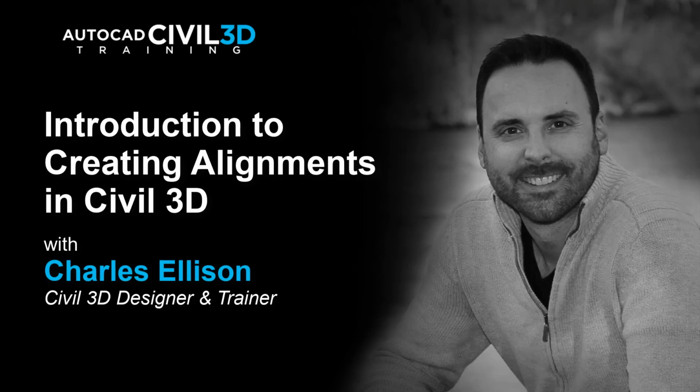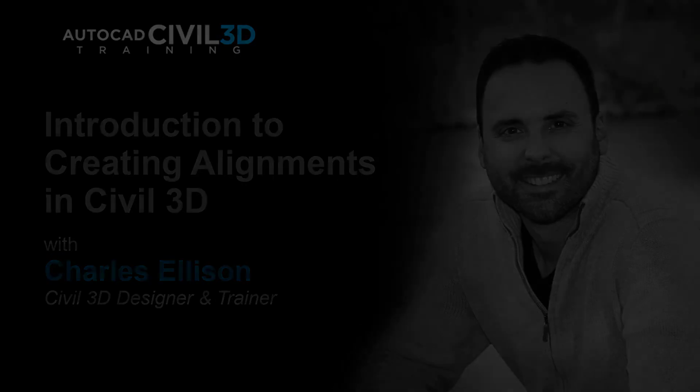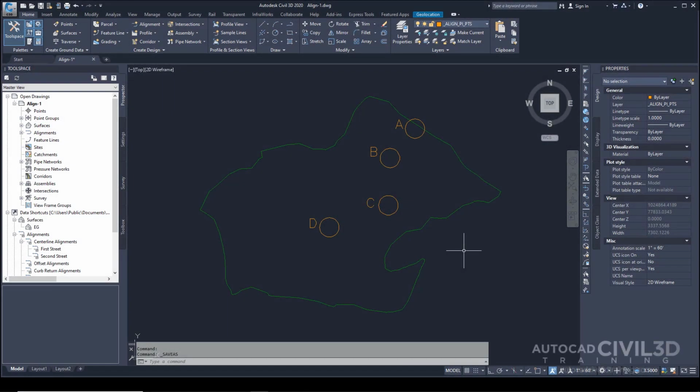You can enter numeric parameter values for lines, curves, and spirals in the Alignment Entities table. If your alignment design must meet minimum standards, you can apply design criteria to the alignment either before or after it's created. The upcoming tutorials will demonstrate basic alignment creation tasks. In this exercise, you'll use the alignment layout tools to draw an alignment that has curves.